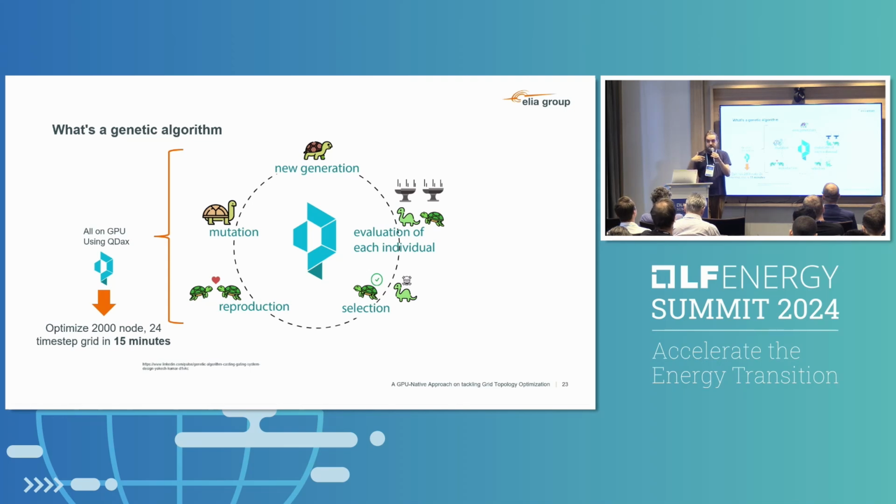But the idea here is that we assume that what the operators do currently is not optimal. Their actions on the grid might be stable, they are safe, but they are not optimal. And the idea is we don't want to take in any constraints based on historic actions, like imitating the behavior of the operators, because this would constrain us to the set of seen topologies.